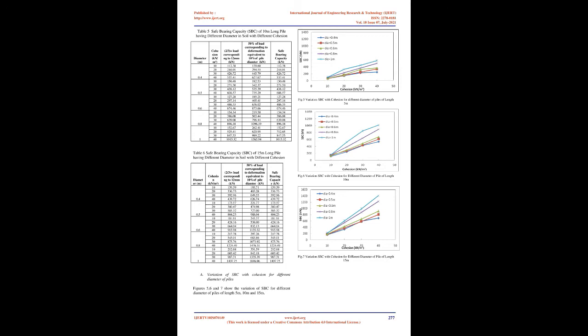With respect to the pile, parameters like modulus of elasticity, Poisson's ratio, skin friction per unit length and end resistance are required for the analysis. The skin friction per unit length and end resistance of pile were determined as per the guidelines specified in BIS for the calculation of pile capacity in cohesive soil, and accordingly, the following equations were used.